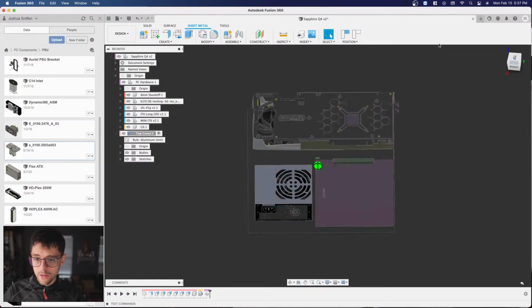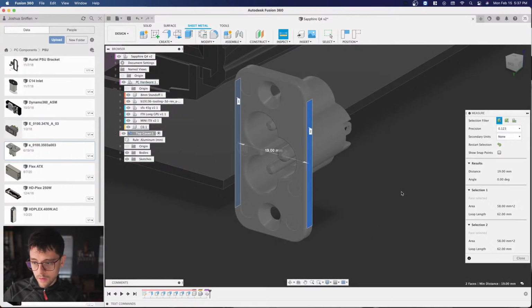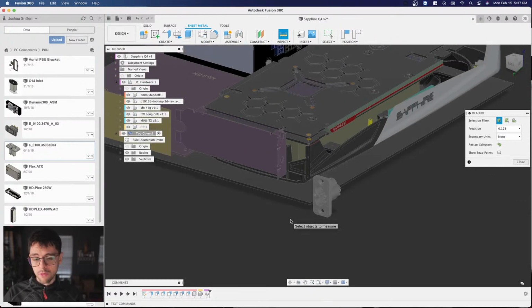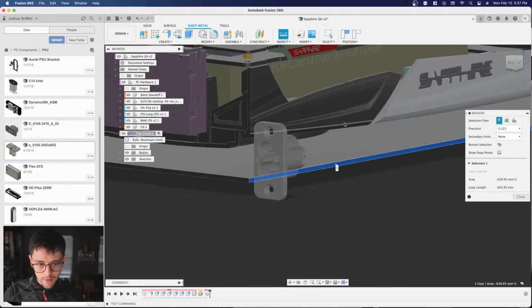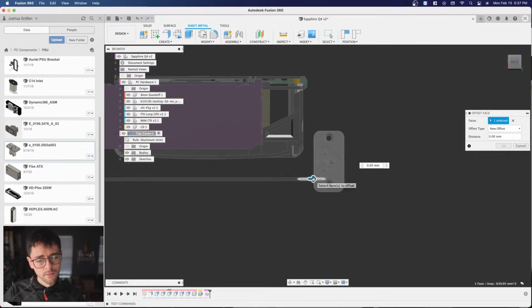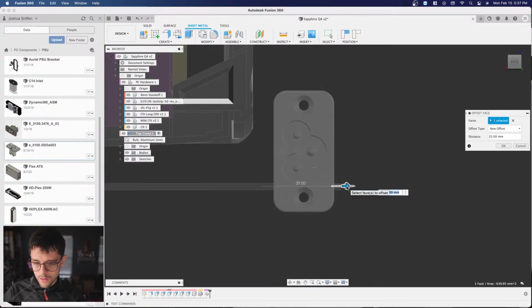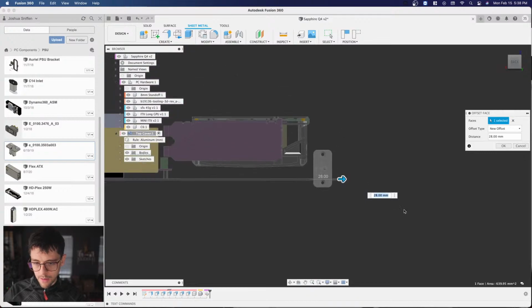I need at least 16 millimeters for my on-off switch, which I might not put in the back. I might put it in the front, but just to be safe, this is 19 millimeters, so I have plenty of room, because a 16 millimeter on-off switch has a 19 millimeter front head, so I just got to remember that. And I'm going to extend out my bottom cover to make sure that I'm going past, obviously, my C6 connector. And I'm actually going to go out 5 millimeters more. I think that will look fine and dandy.